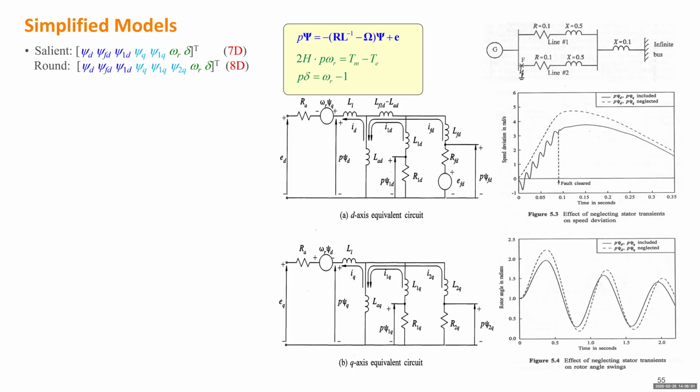Because this is actually the major source changing the power output from the generator. Not those others. Those only determine the transient or subtransient dynamics. Similarly, under steady state condition, those two will be directly connected. So those won't influence the power output much. Okay, then we can do a test. We just add a disturbance at the terminal of the generator, and we compare two models.